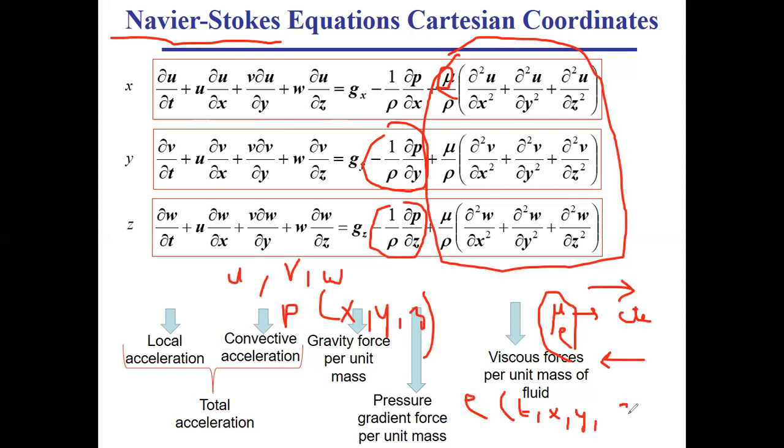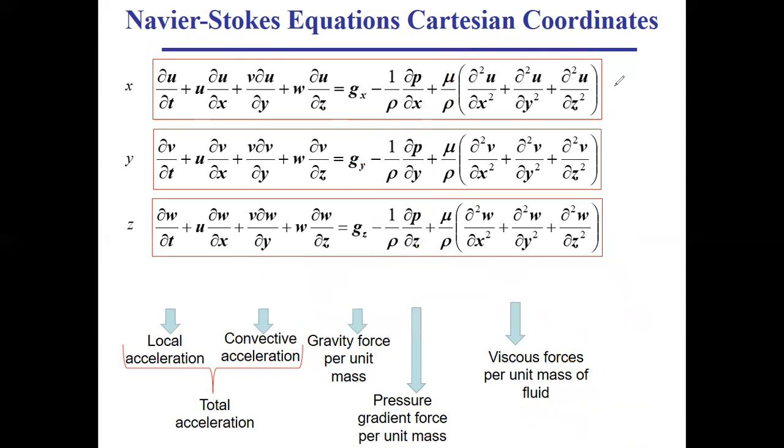So Navier-Stokes is a particular case for fluids that have constant viscosity and constant density. In case these are not constant, you will obtain more complex equations, and you should solve for the variation of viscosity and density in addition to velocity and pressure with space and time. So already Navier-Stokes are really complex equations, and they don't always have an analytical solution. They only present analytical solutions in some simplified cases that we talked about, like laminar flow in ducts, in pipe systems, flow between parallel plates, etc.